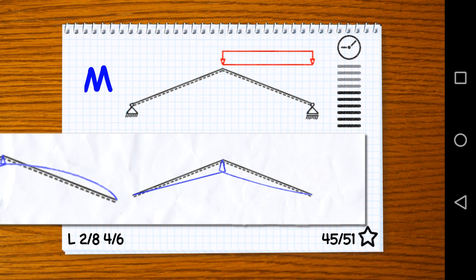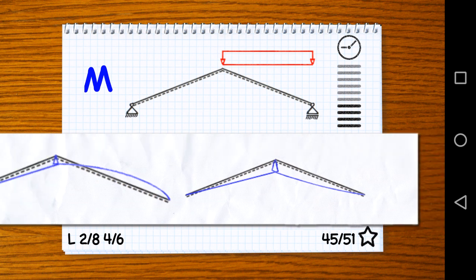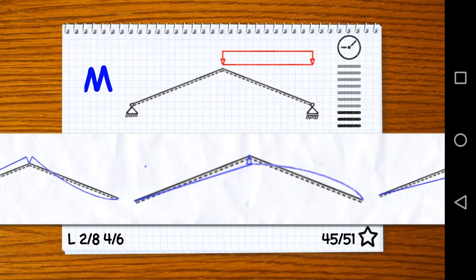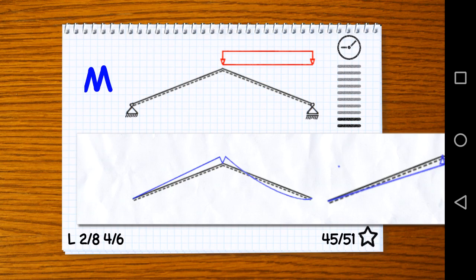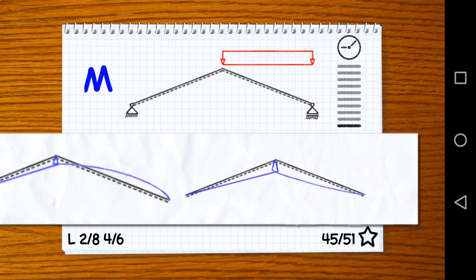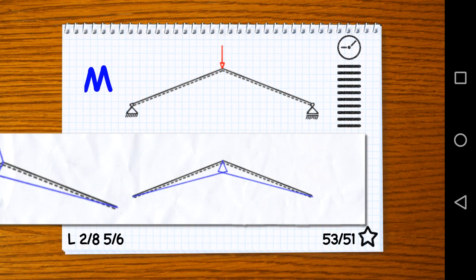And due to that vertical force, we're basically gonna have a positive moment first. We don't have to forget the distributed load that would lead to a quadratic distribution. So this right answer here looks really good. Here the curvature of the quadratic distribution is wrong. And over here, there's no reason for that moment to change signs. So the right answer was correct as I said earlier.